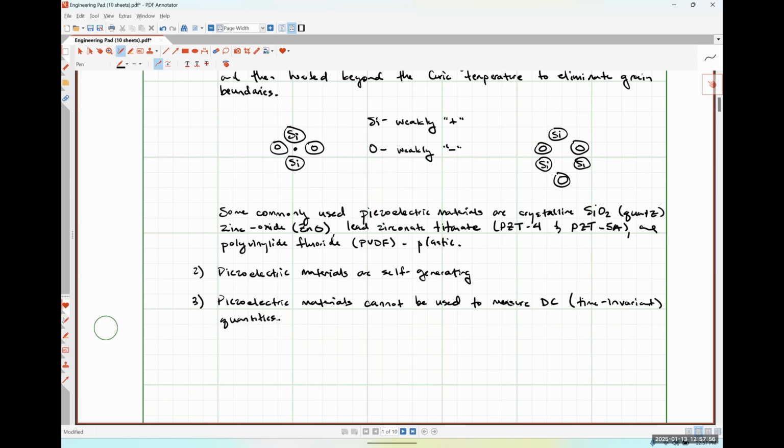So we'll get to this in the math here in a couple of minutes, but essentially the piezoelectric response is caused by a change in the material's shape. And so we'll generate a signal every time the material changes shape. So if we just squeeze it, and then we hold that squeeze, we've generated effectively an impulse of voltage. And it's not until we decompress that we'll also generate another voltage and so on and so forth. So we have to be constantly deforming the thing in order to generate a continuous signal. Otherwise, all we're going to get is just impulses, okay?